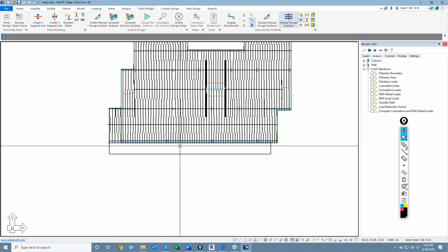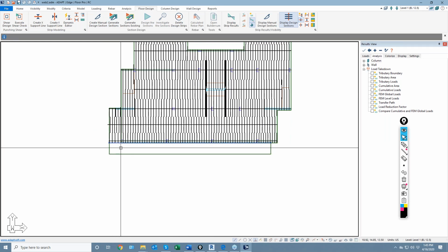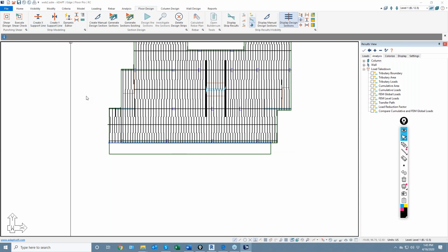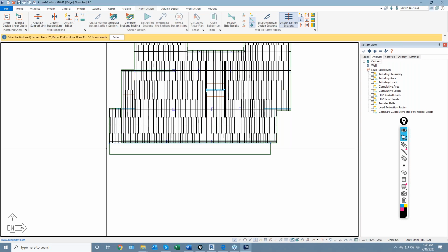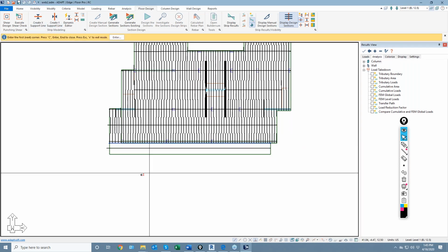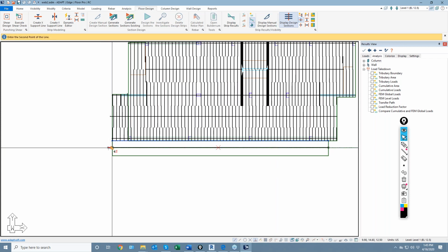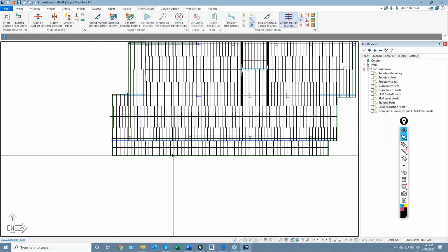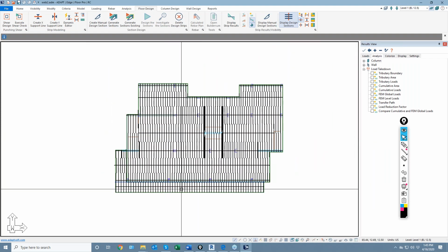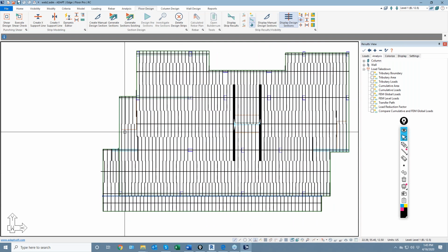Now I don't have any strips down here because there's no support line below the splitter. So I can add another splitter if I really want to get some results along that direction of the balcony. Something like this, and then I can regenerate my strips. And you can see there are strips that enter into openings.